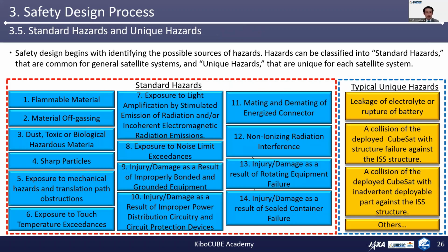So in this slide, I'd like to introduce the definition of standard hazards and unique hazards. Safety design begins with identifying the possible sources of hazards. Hazards can be classified into standard hazards that are common for general satellite systems and unique hazards that are unique for each satellite system. In the left figure, standard hazards are listed.